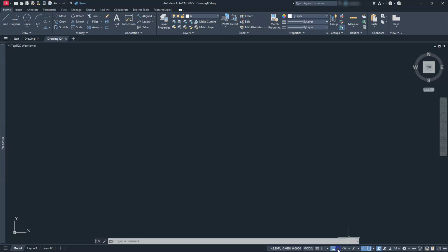Let's go ahead and turn our ortho on. It's another normal thing we do. And then from here, I'll let you go ahead and take a look at the running O snaps that I am going to have on for this video. Okay, let's start off with the line command. And all I'm going to do is select here, and I want to go down a distance of 75, right? So I'm going to type in 75. It typically will run off your paper.